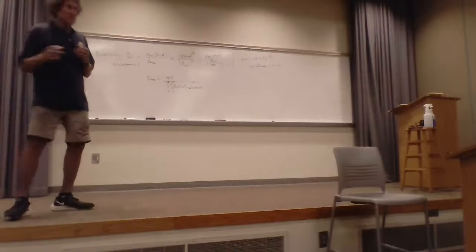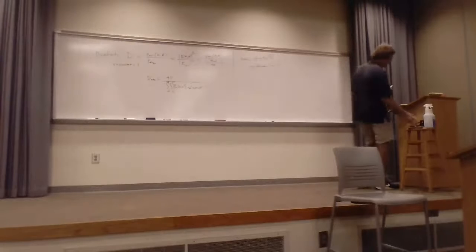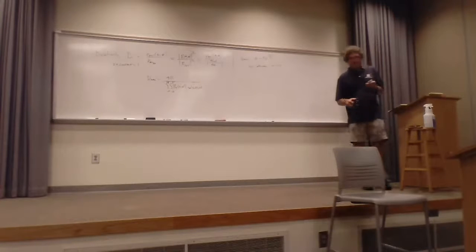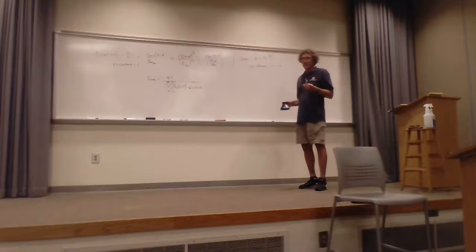Here's where it gets important. Pay attention. So, one of the things is, well, what could cause the efficiency to be less than 1? Ohmic losses. Anytime you have current in a wire, and if you have a wire antenna, you're taking some of that power and it's heating up that wire, and that means there's power loss there. Y'all follow me on that? So that would do it.